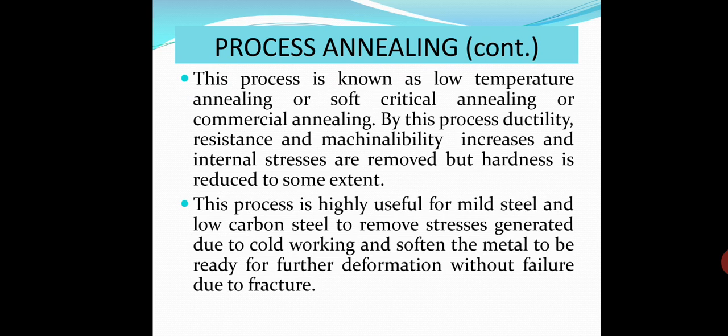This process is highly useful for mild steel and low carbon steel to remove stresses generated due to cold working and soften the metal to be ready for further deformation without failure due to fracture. That is why the name is process annealing. It is done after the cold working process to make ready the low carbon steel or mild steel for further deformation.